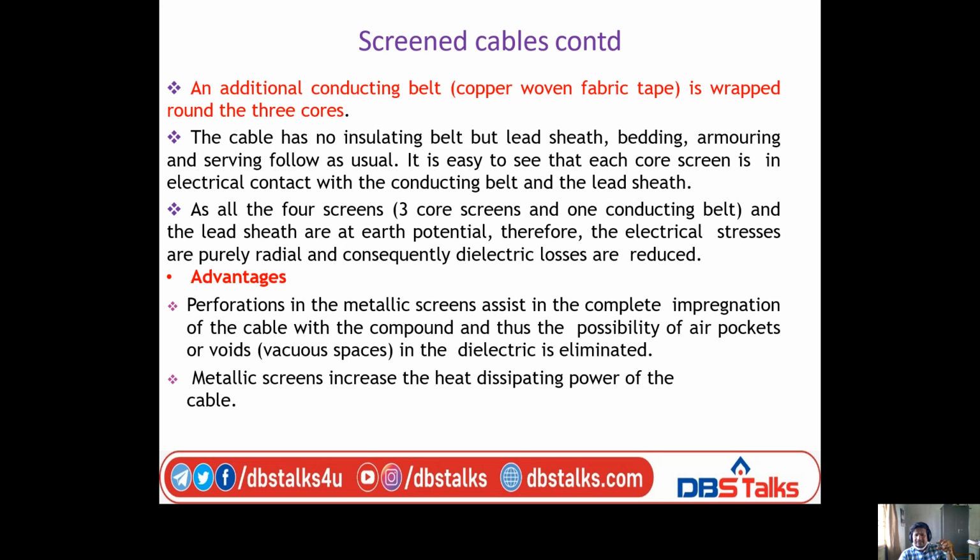The electrical stresses are purely radial and consequently dielectric losses are reduced. Why? Because it will go to the earth. So that is the major difference between the belted cable and screened cables.